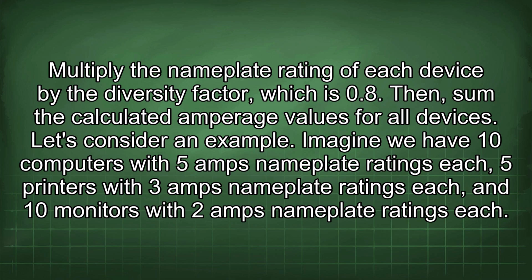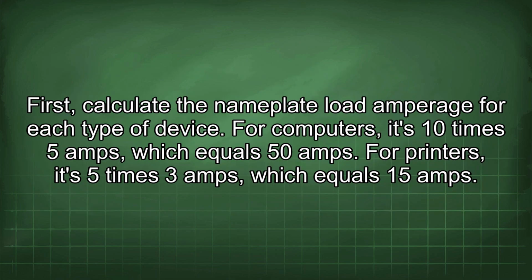Let's consider an example. Imagine we have 10 computers with 5 amps nameplate ratings each, 5 printers with 3 amps nameplate ratings each, and 10 monitors with 2 amps nameplate ratings each. First, calculate the nameplate load amperage for each type of device.